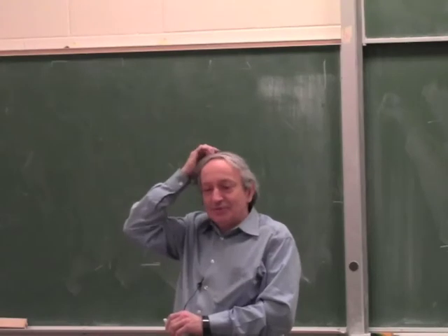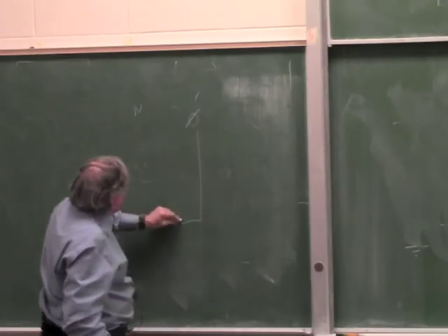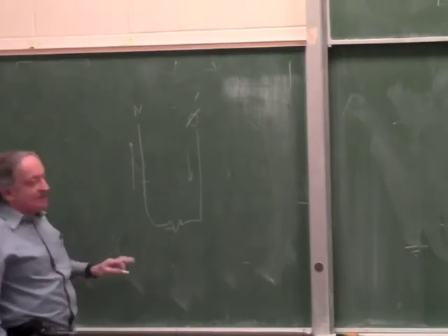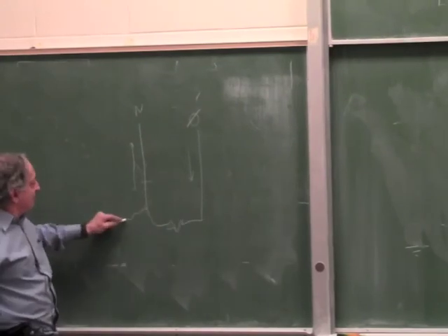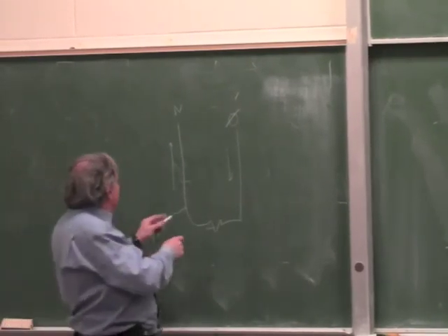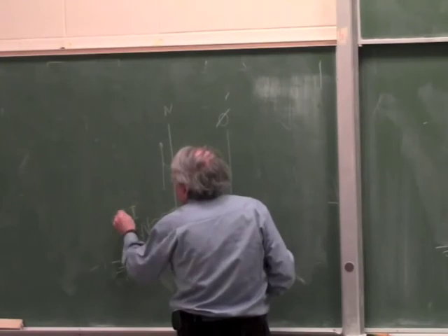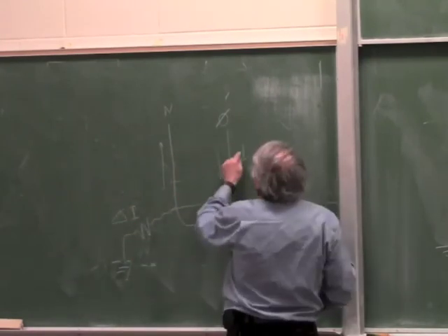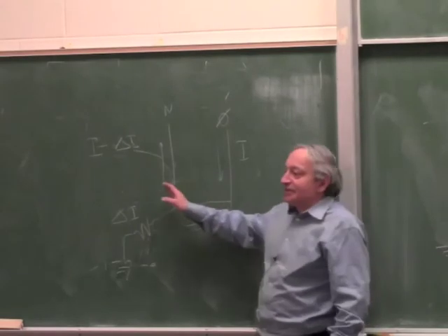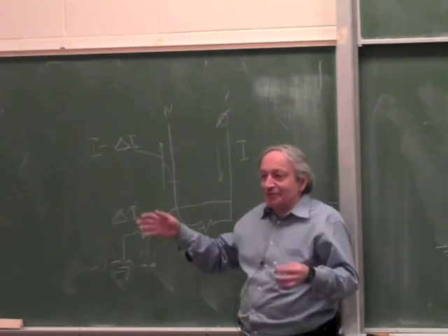Very good. Very good, because if you don't get electrocuted, this is phase, and this is neutral, and this is your load. If you don't get electrocuted, the current coming in as a phase and current coming in the neutral must be exactly the same. Now if you get electrocuted, there is some current flowing to ground. Okay? So if some current flowing to ground, I should draw it on the live side here. If some current is flowing to ground, and let's call this delta I, could be small, could be milliamps, then if this is I, the return current will be I minus delta I. Okay, so if these currents are not exactly the same, somebody is being electrocuted, or there is leakage to ground in the appliance, which is also bad. Shouldn't be used in bathrooms.